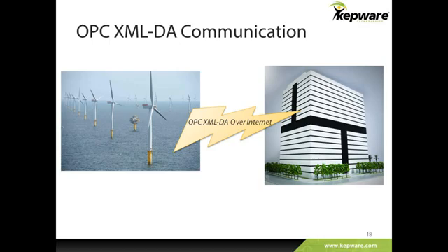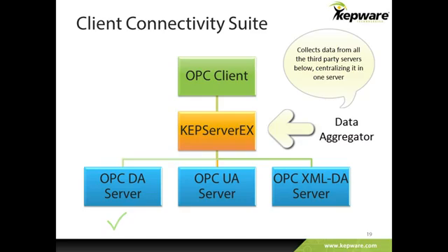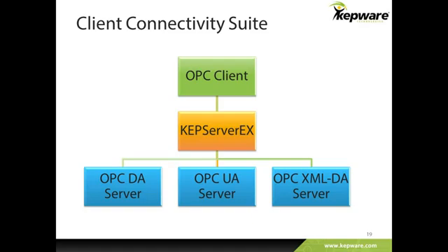Users can connect to any OPC XML DA server using this new driver. For example, users may now monitor data from the Siemens SiMotion controllers with embedded OPC XML DA. This driver will be included in the OPC Connectivity Suite alongside the OPC UA client and the OPC DA client driver. These client connectivity options allow KEPServerEX to act as a data aggregator, unifying your data into one source from any of these OPC servers on a subscription or pulled basis.